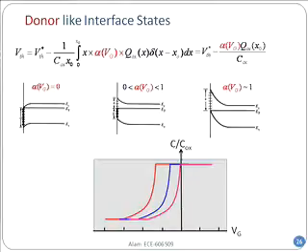Now, of course, this is going through this phase as a function of voltage. So it's as if the threshold voltage keeps changing as you keep pulling the bias. So the real curve you will be seeing is not these separate three curves. What you will be seeing is a transition of this curve among these curves from one to another. Now do you see? You have stretched things out. I have just shown you three discrete points. Of course, it will be a continuum of points, and you can see therefore the green will become a continuously stretched out CV characteristic. You see that, right?